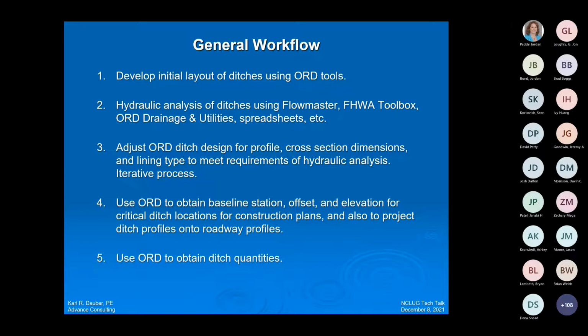And then come back and adjust the ORD ditch design based on that hydraulic analysis, adjustments to profile, cross-section dimensions, and lining types. And then once the ditches themselves are done, you can use ORD tools to obtain all the information you need for construction preparation and construction layout: baseline station, offset, and elevation for those critical locations that the contractor will need for construction. You can also use the ORD data to project ditch profiles onto the roadway profiles. And then lastly, you can use ORD to obtain ditch quantities as well.